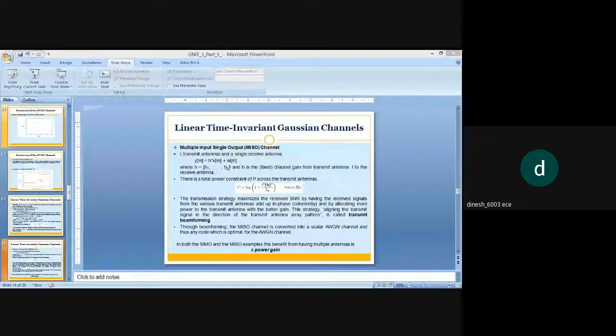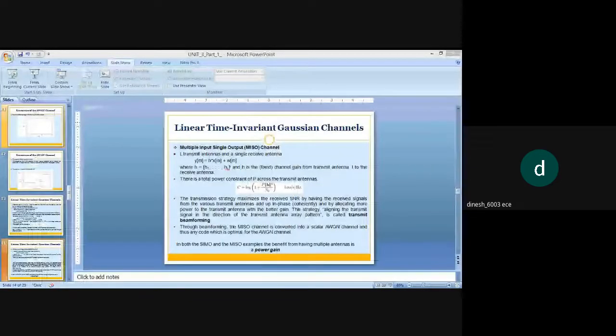The optimal power allocation will depend upon the coding, being obtained as C_n, the capacity of the transformed channel with Nc tending to infinity, which will become the maximum over P_0 till P_{Nc-1} of summation n=0 to Nc-1 log(1 + P_n |h_n|^2 / N_0), where summation n=0 to Nc-1 P_n = Nc times P, and P_n is greater than or equal to 0 where n is equal to 0 till Nc-1.